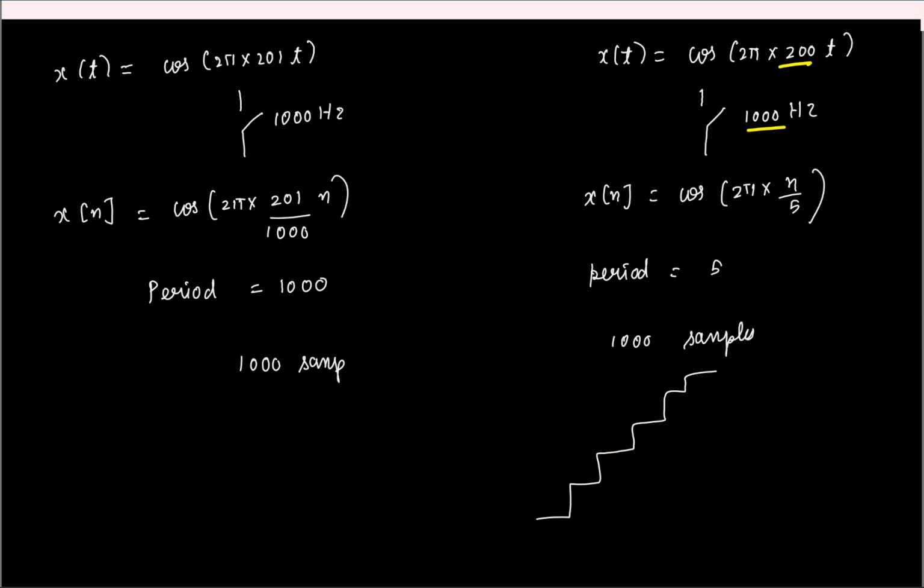So the bottom line is, as long as you have busy signals wherein you span the entire range of the quantizer and make sure that there is sufficient variation in the signal amplitudes from sample to sample, the assumption that the quantization error's probability density function is uniform is valid quite well. And that's what will happen in real life. The real life signals we encounter will all be busy signals. So this works quite well. So now that we know its PDF, let's make some more calculations on its statistical quantities.